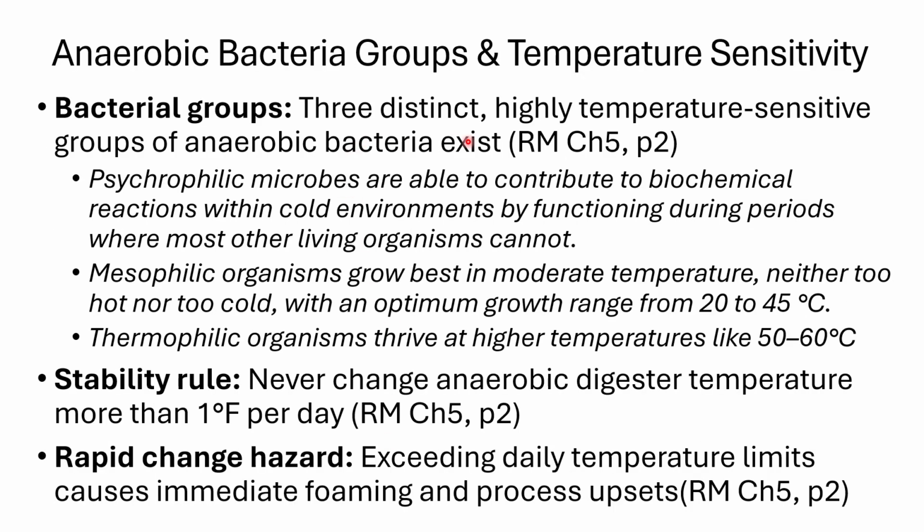Okay, let's take a little bit of a step back and talk about the bacterial groups we're dealing with. We've got three very distinct and temperature sensitive groups of anaerobic, again without oxygen, microbes. They exist and they're needed for this process. We've got these psychrophilic microbes, and they can contribute to these biochemical reactions of converting complex organics to organic acids, then into methane gas.